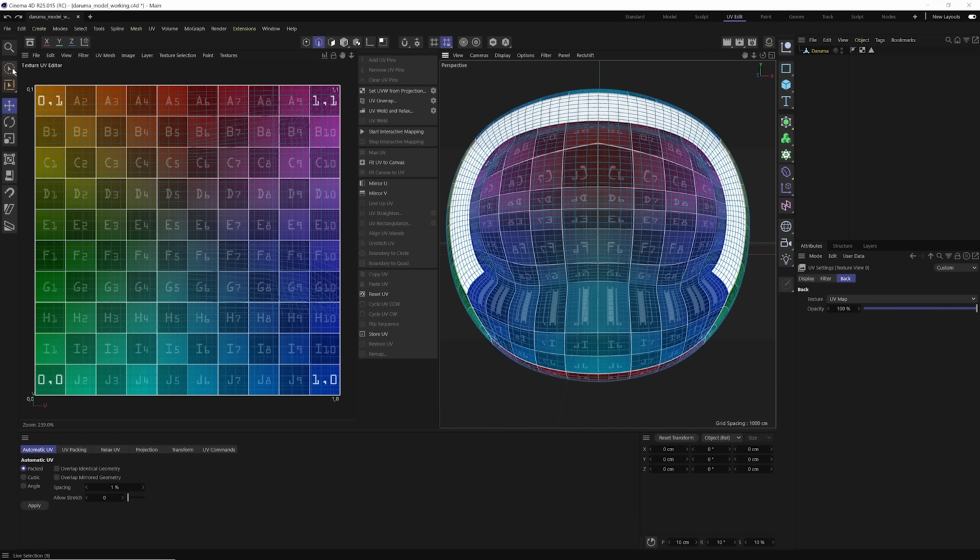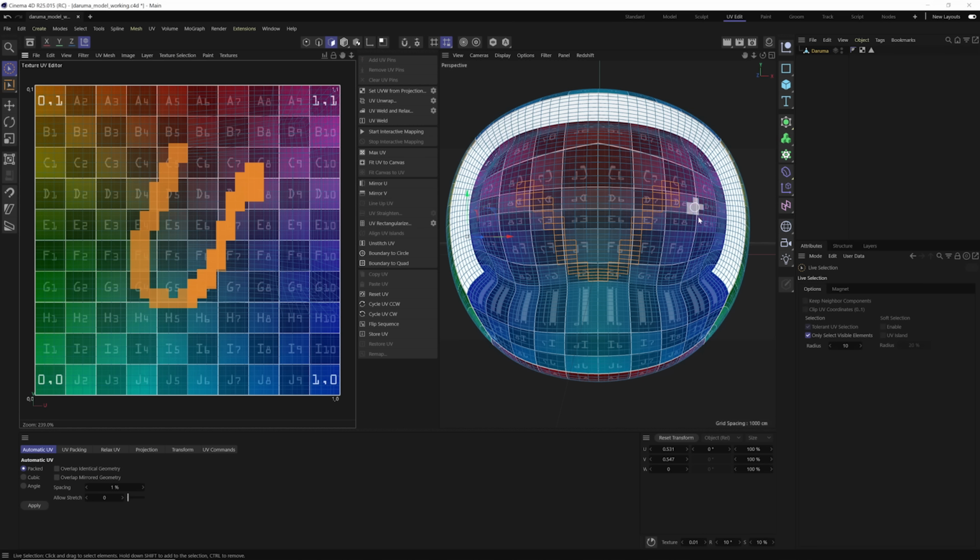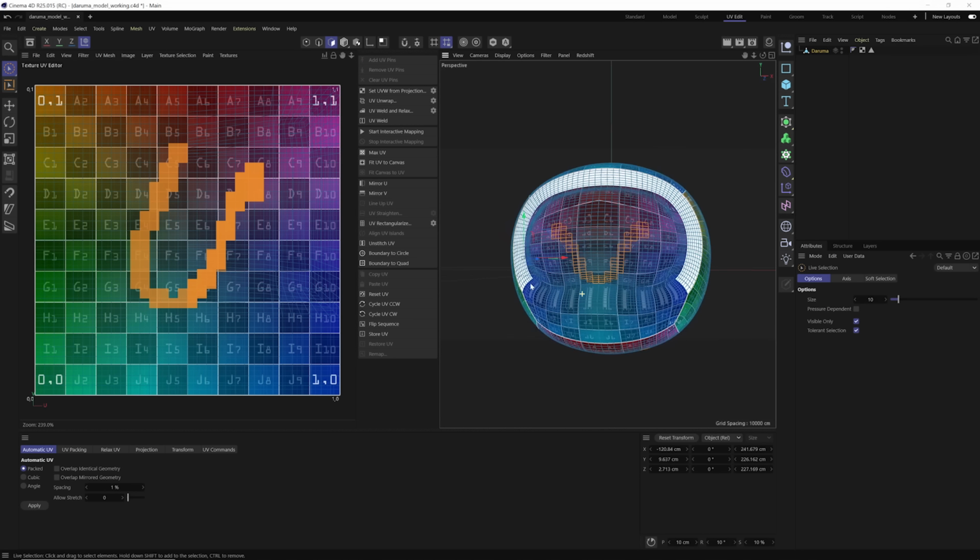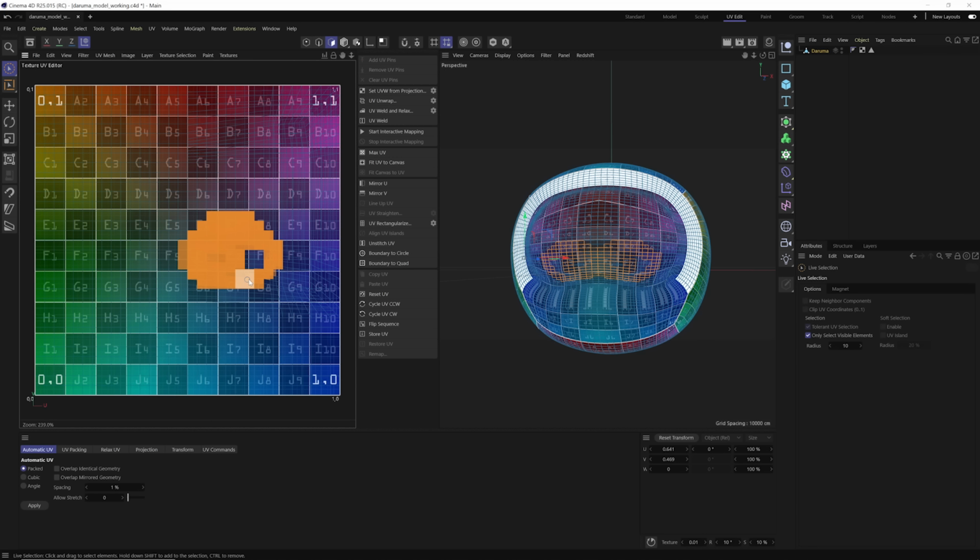And if I go and select some of these polygons here, you can see I'm selecting a symmetrical version of it, and you can see that these polygons are actually overlapping each other on this UV map. If we were to export this out as is to Procreate, it would almost be like trying to paint the Mona Lisa on a canvas that's folded into an origami thing or crumpled up into a ball. You want to have a flat canvas that you can paint on, and as of right now, this UV is what the kids say hot garbage. It's not going to be good for Procreate.